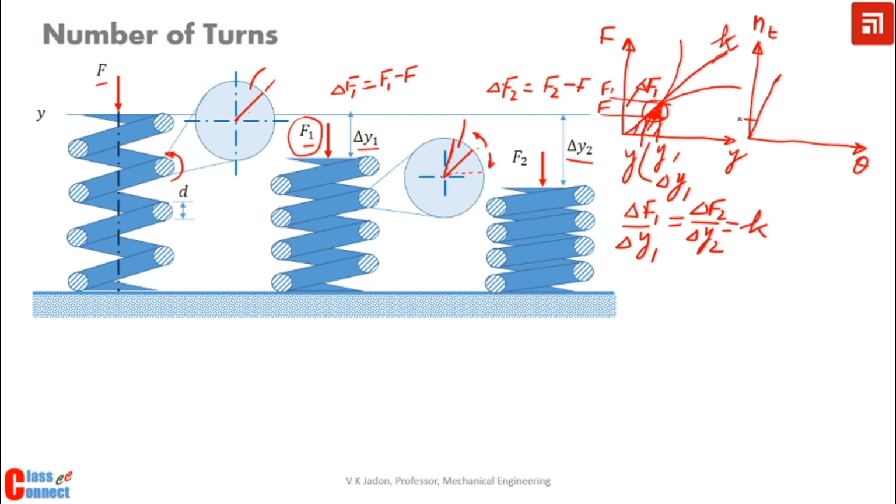So this is MT and corresponding to this is MT1, and likewise we have delta theta 1, and we can find out the strain energy. If we start from 0, then it is half MT into theta, and if we take only the change in the load, then it is half delta MT1 into delta theta. So this is how we can find out the strain energy.